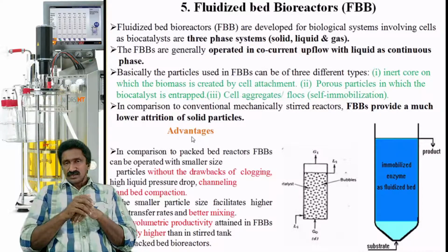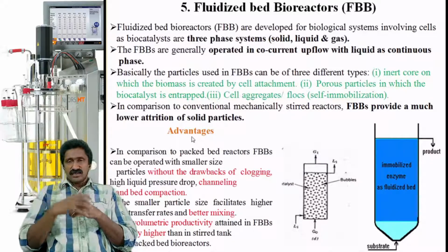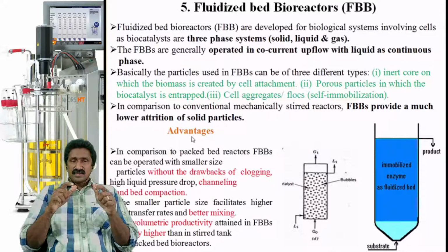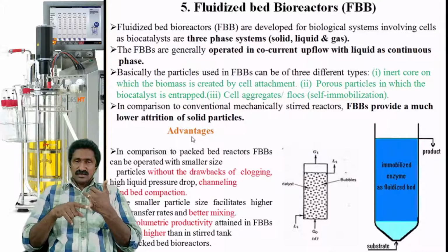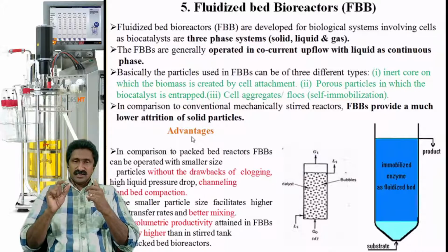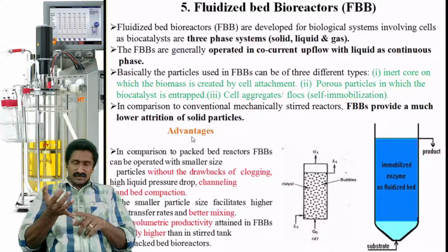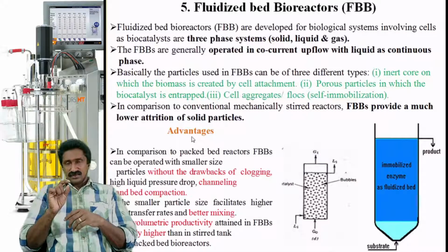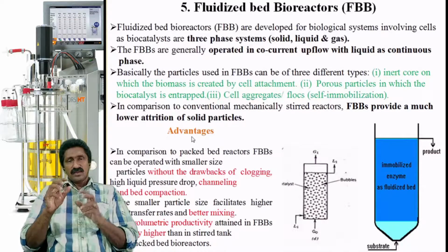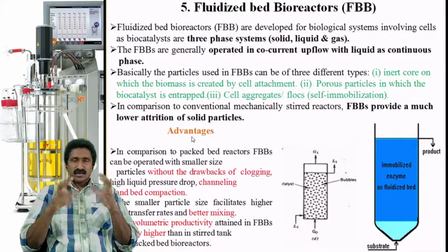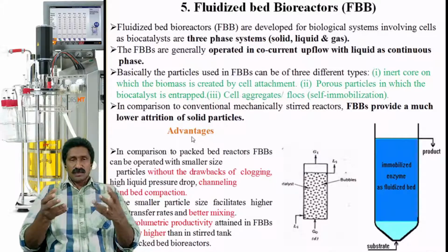Then smaller particle size facilitates higher mass transfer rates and better mixing. That's another point. Since the particle size in this fluidized bed reactor is small, it facilitates high mass transfer rates. Similarly, smaller air bubbles will provide larger surface area, and better mixing and better aeration are ensured when you are creating smaller bubbles.